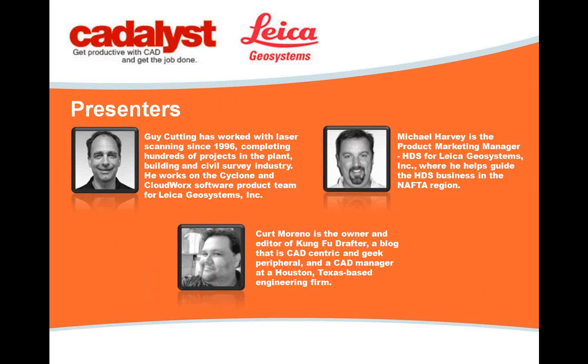The answer is no. Cyclone is our own standalone software, so you're going to need to learn certain portions of it, especially registration, which is the act of merging multiple scans together, sometimes in the field. Once you're there, the workflow is rather linear: you collect the data in the field, bring it into the office, and register it together, merging the scans. At that point, the workflow just explodes into a gazillion different directions.